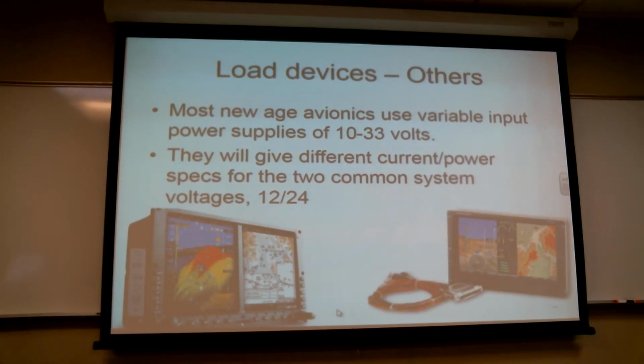The upside of all of this new fancy, newfangled stuff is it does a whole lot more with a whole lot less weight and a whole lot less power consumption. Almost always when you go to upgrade avionics, unless you're keeping up with the Joneses and all the whistles and bells, even though you might expand features, you are generally going to be reducing the amount of current the generator has to produce. You also oftentimes will be making the airplane lighter.